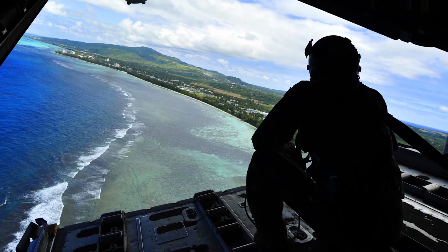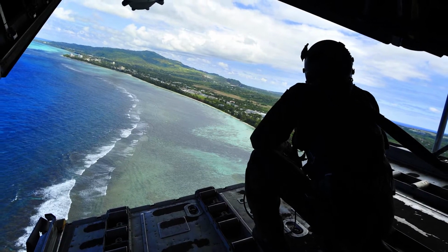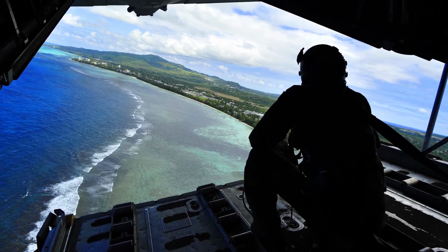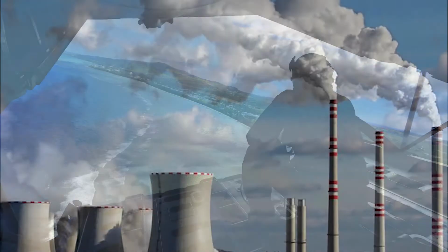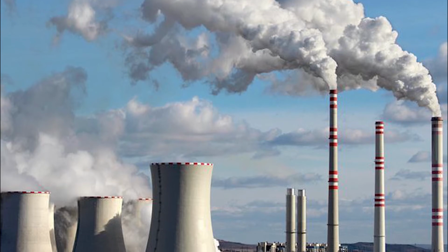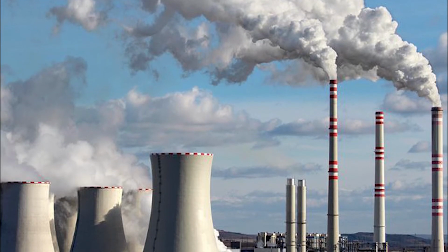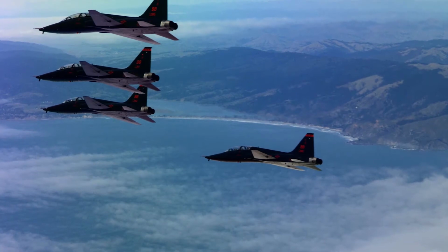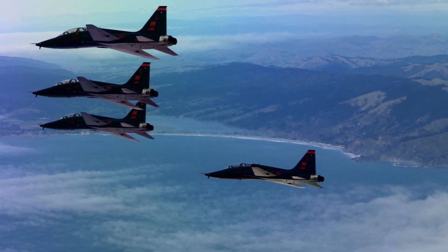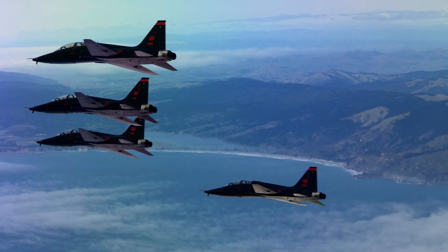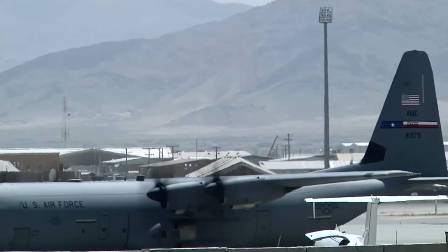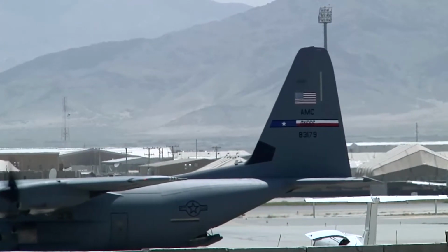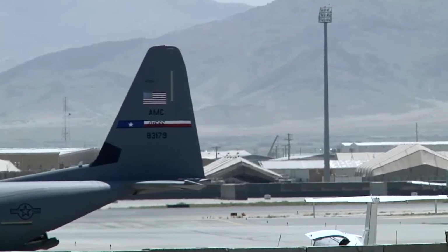Familiarity with local and deployment area conditions is important for understanding each area's environmental impact on corrosion. One of the most corrosive environments is found in coastal regions with high humidity and salt concentrations. Dissolved salt forms an especially strong electrolyte. Industrial areas can contain pollutants that are released into the atmosphere and create harsh corrosive environments. Geographic areas with sand, dust, or volcanic ash present another unique corrosion problem. When these fine particles are deposited on surfaces or penetrate sealed internal areas, they can promote corrosion by blocking drain holes and increasing temperatures.